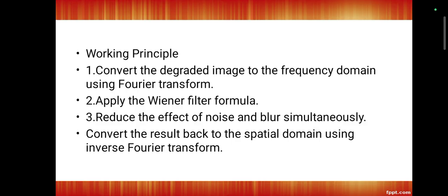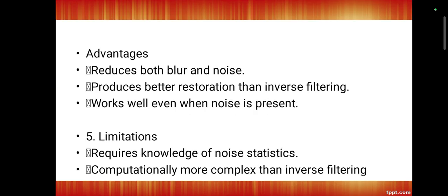The working principle behind this Wiener filtering is: convert the degraded image into the frequency domain using the Fourier transform, apply the Wiener filter formula, reduce the effect of noise and blur simultaneously, and convert the result back to the spatial domain using the inverse Fourier transform.